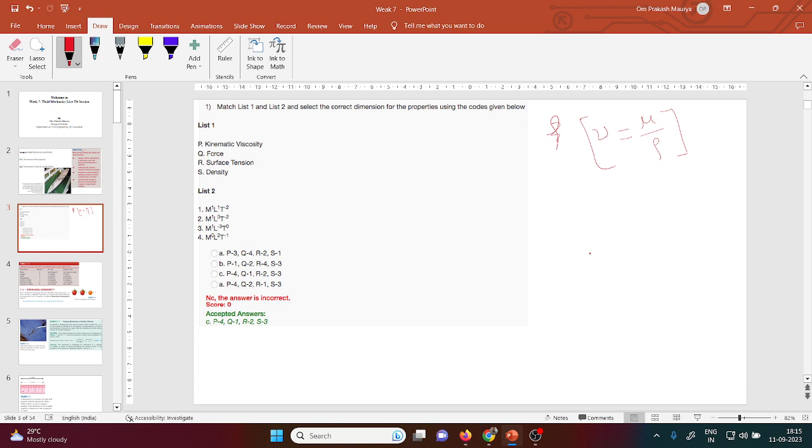You all know the principle, Newton's law of viscosity: tau is equal to mu du by dy. One thing I want to tell you: this relationship, Newton's law of viscosity, is valid for laminar flow, not turbulent flow. So this is the very basic.